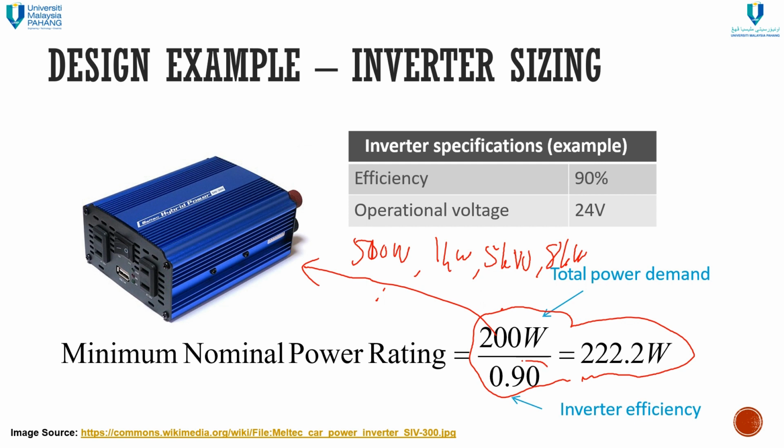Please find an inverter that has a datasheet that states the inverter efficiency. You need to Google a bit more. Look for an inverter that has a datasheet. Yes, now we have hybrid inverters. It's okay, you can take the datasheet and check the spec. The better one is compatible with 12 volt, 24 volt and 48 volt, the majority of system voltages. That's the better one, but usually the price is higher.